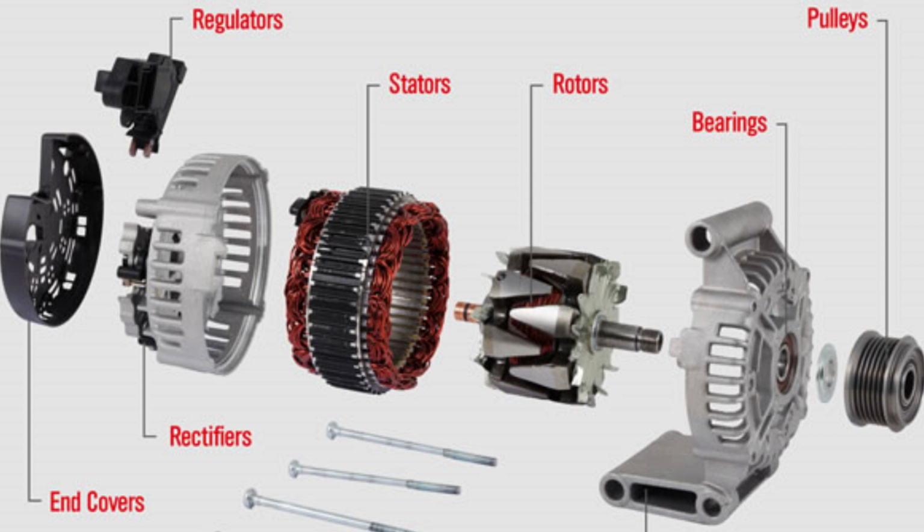Diodes. Alternators use diodes to convert the AC produced by the stator into direct current, DC. Diodes are electronic components that allow current to flow in only one direction. They are arranged in a configuration called a rectifier bridge or rectifier assembly.